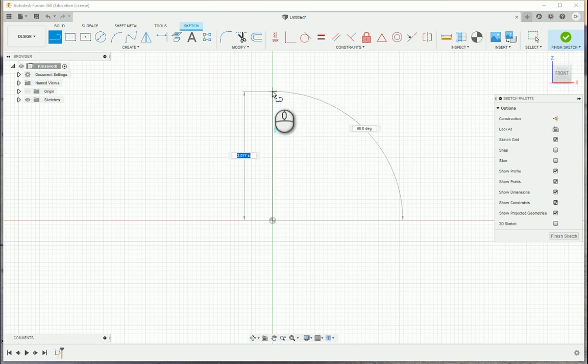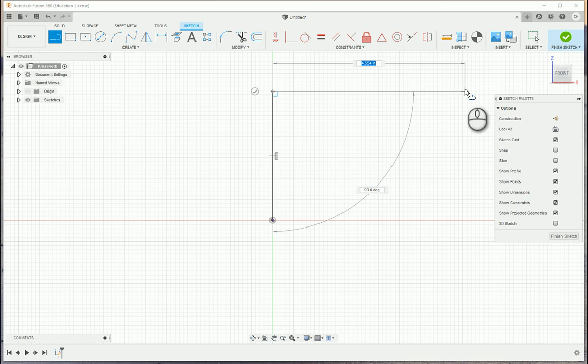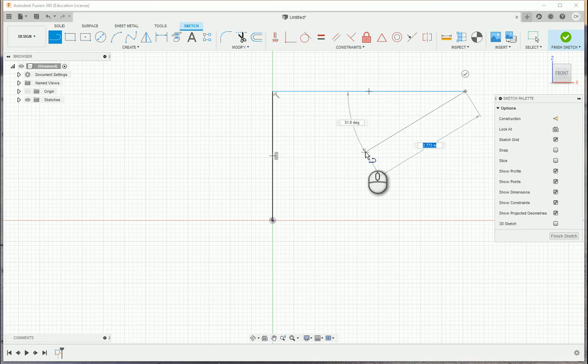So let's say I do about 3 inches, and then if I go across, let's say I make a rectangle of about 4.5 inches, and I can click. If you notice here, as you get close, you'll see these blue dashed lines. Here I'm getting the midpoints from those previous 2 lines. Those dashed lines are helping me, and you'll notice your line snaps into place. It's helping me maintain a 90-degree angle between that last line that I just drew.